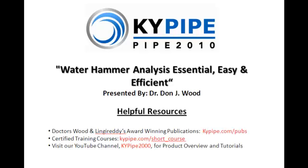Okay. The next question, again from Jeffrey Rosalind. Have you experienced the valve manufacturer's tables and nomographs for sizing surge anticipation valves, SAVs, or pressure relief valves based on pipeline size and flow rate to be accurate, or should a surge analysis still be run to verify sizing and timing on the valves? Did you understand that? Yeah, I do. The timing should be based on a surge analysis.